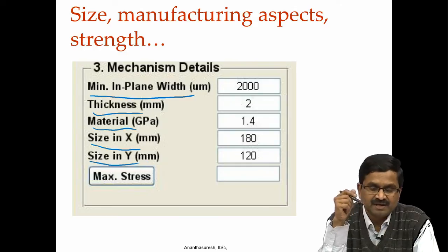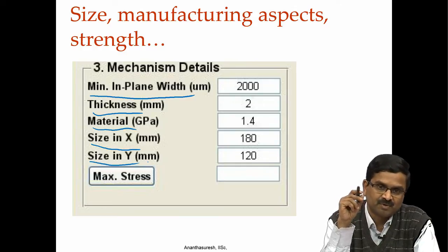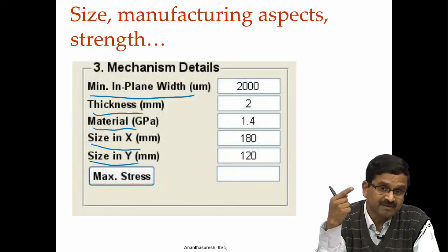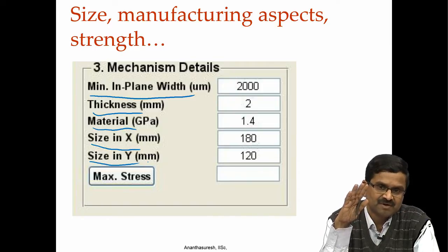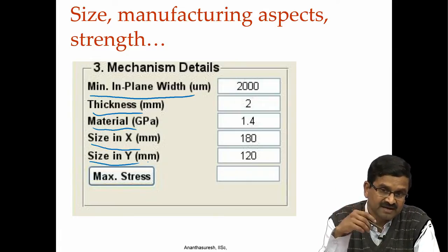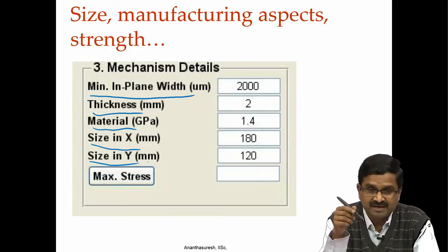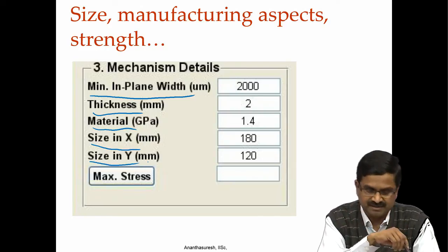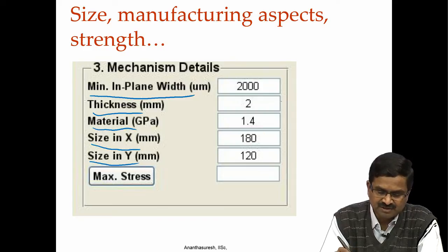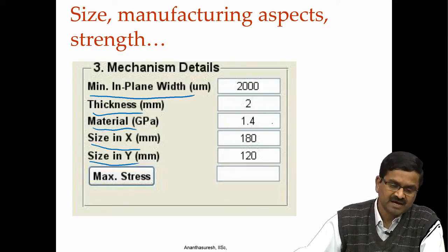and at that point whether n lies within the range corresponding to that point, because every point in the feasibility map, KCI KCO, stiffness map or feasibility map will also have an n, because what we are seeing is only a projection of a 3 dimensional volume containing the feasible values of KCI KCO and n. So, n will be there, that n has to agree with the n of the compliant mechanism. So, we try to change and we put some limits on these, we can change thickness, material and all of that, and try to see.